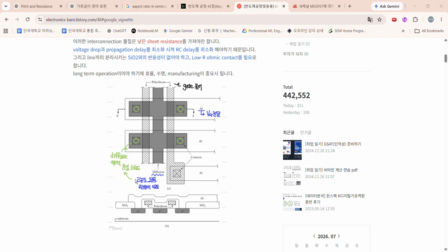So these materials are used for modern industry, and Applied Materials use a machine. The machine name is Endura, and they deposited ruthenium cobalt. They used a double layer, ruthenium cobalt. Originally the double layer was, as I remember, TiN or TaN. These double layers were used, but from their research, cobalt, ruthenium, and molybdenum have a very low mean free path, so they can have good resistivity in shorter pitch. So they developed the ruthenium cobalt binary liner.